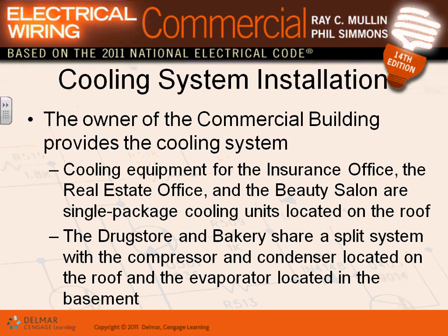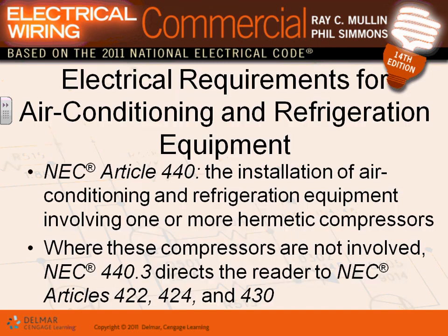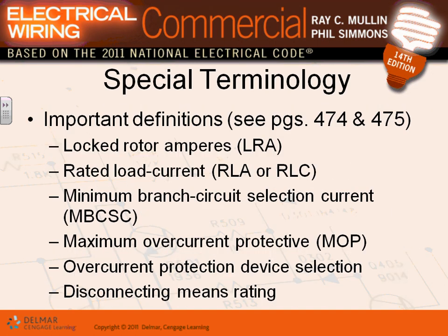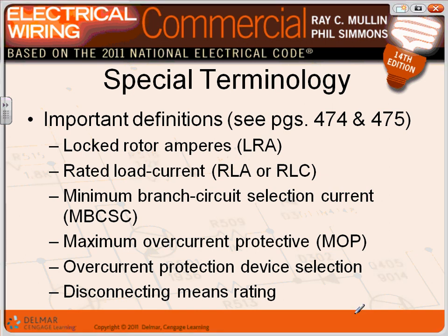Okay, the control system. This just talks about what we're doing in the building. In the NEC code book, guys, there's a couple of terminologies that you have to get used to. Rated locked rotor amps. Remember how we size the disconnect based on this one. If the compressor doesn't start, that's the highest amount of current that you can pull if the motor is locked.